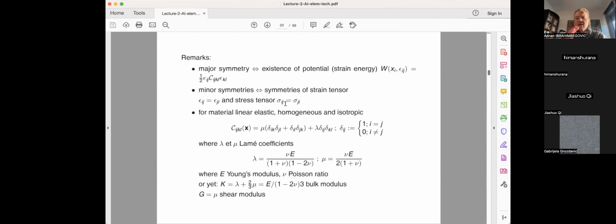If these things are not aligned at 90 degrees, well, you can have anisotropic and so on and so forth. If isotropic, that means the behavior is the same, whatever the preferred direction you want to study. So in this particular case, it so happens that one can characterize the behavior of the material only in terms of 2 coefficients.